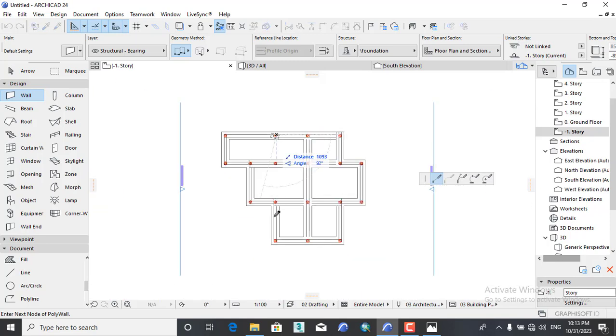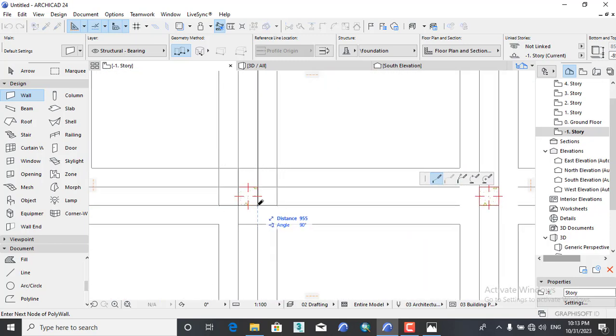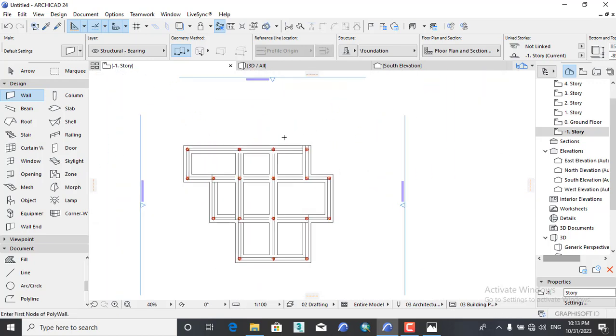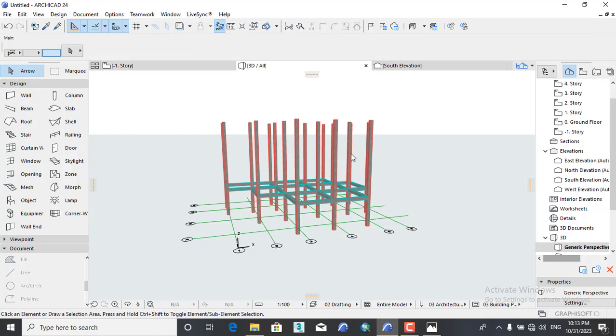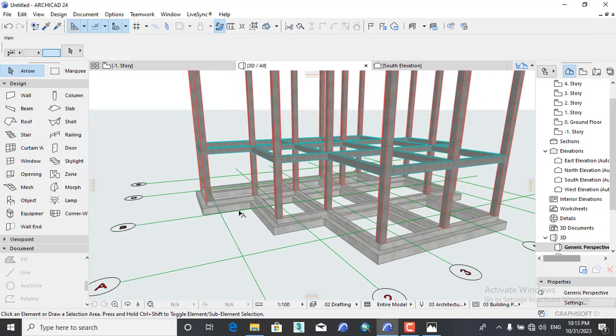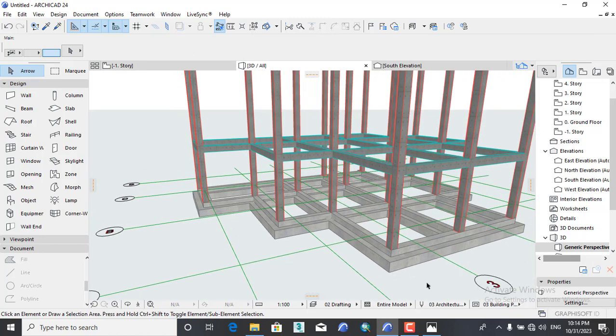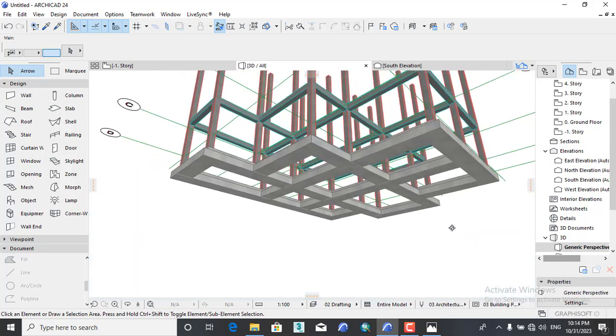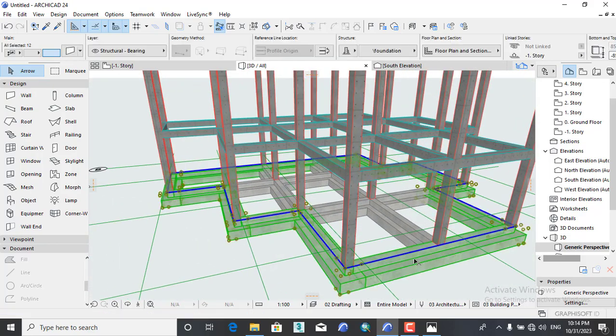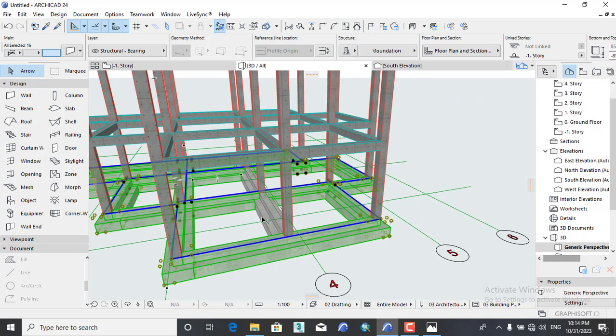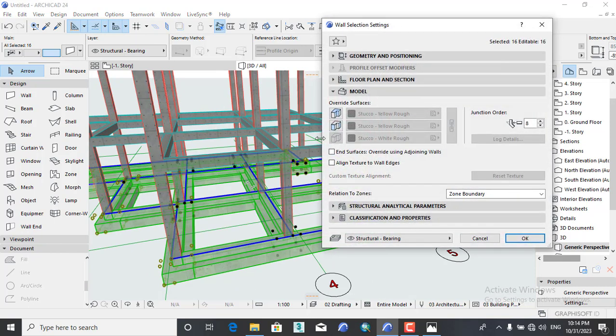It's a through foundation, because it's more secure and safe than separate or individual foundations. We can recreate the foundations. Look at this one. It's very simple and easy. Then select all the foundations that you used here. Press shift and select all of the foundations like this. And this one. Press Control with T.